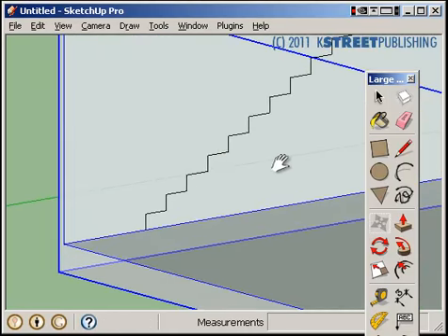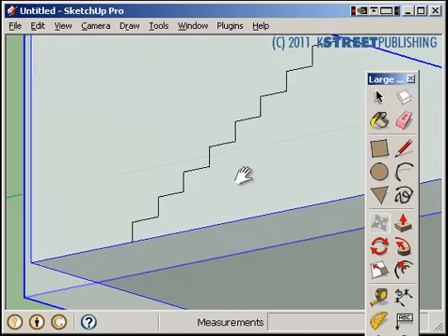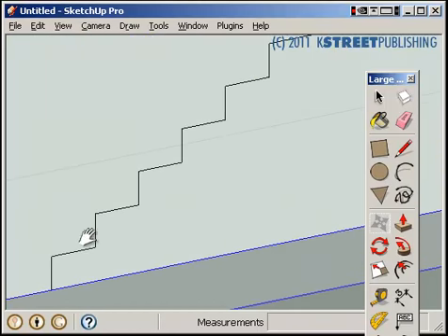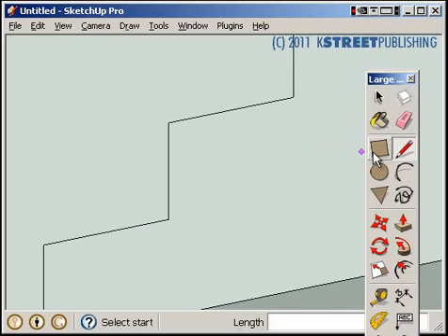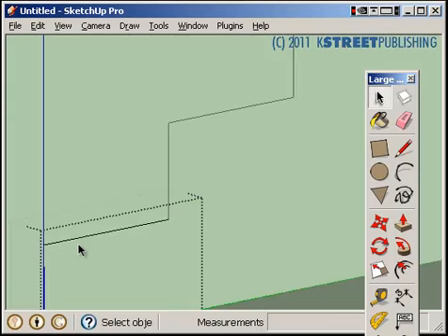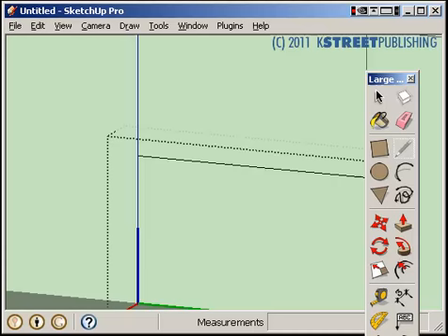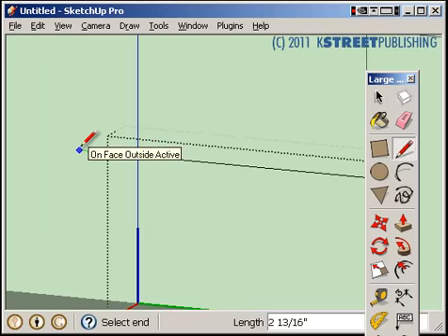So the next thing we need to do is determine how we are going to define the nosing and the depth of the base of this. We need to draw the nosing. So to do that, we go into our component, click on it again, so it's an individual component, and we can work on it independently. We're going to rotate this around, then we're going to draw a nosing. Pick a line here, pull it in the green direction,